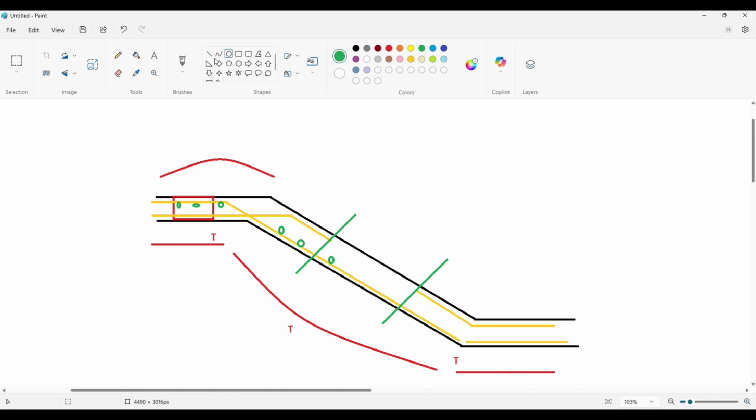Now in some cases, because of additional demand of reinforcement or requests from the clients or the contractors, could be any one of these people, we end up providing additional bars also. Okay, these bars are very rare, but we end up providing them, and the spacing between these bars is also filled by the distribution bars. All right, in some rare cases we have done that, not in all cases, but generally this is what your staircase reinforcement will be like.